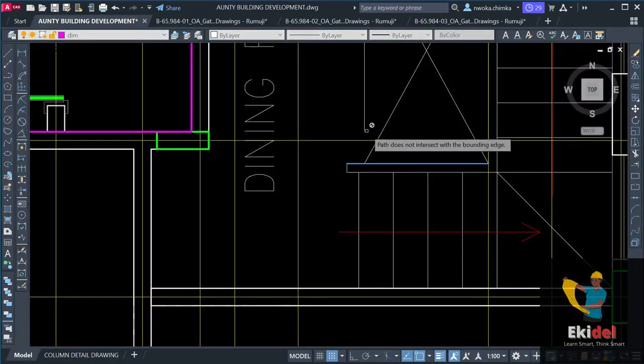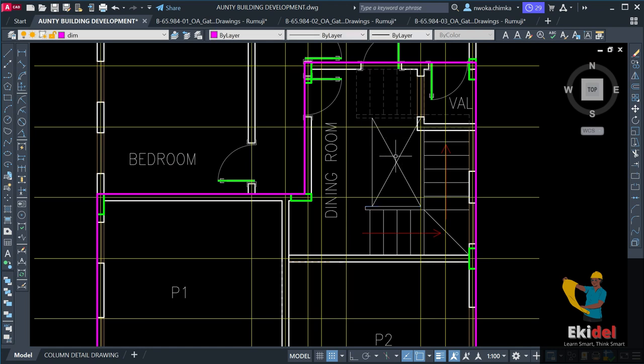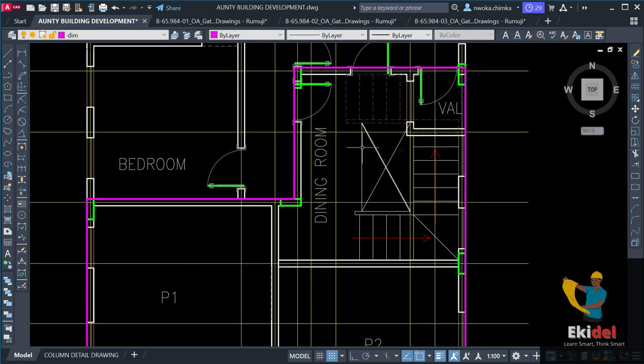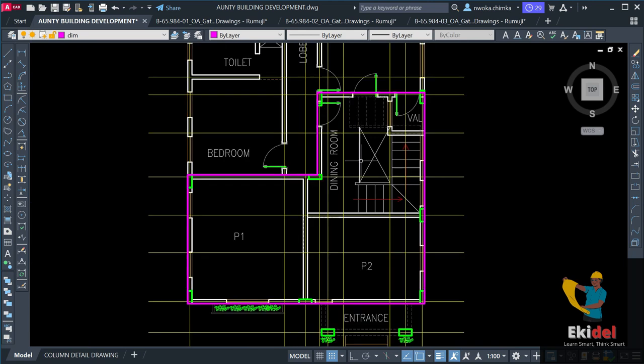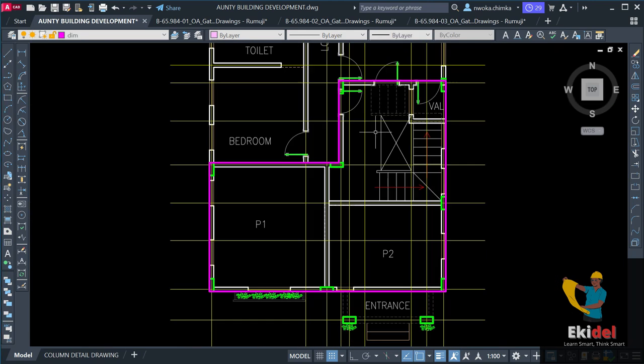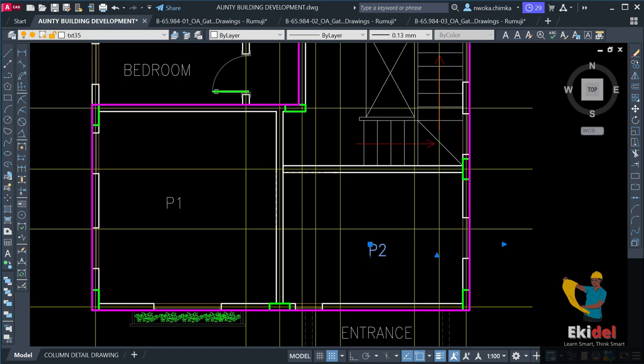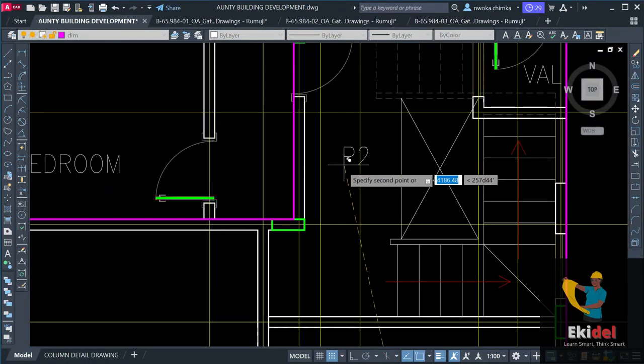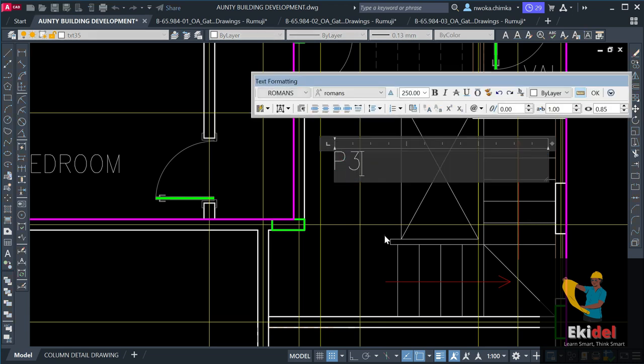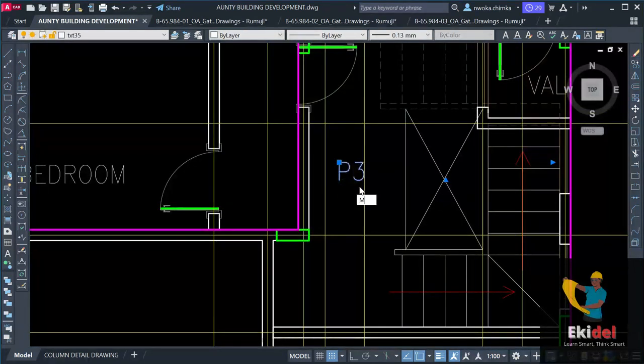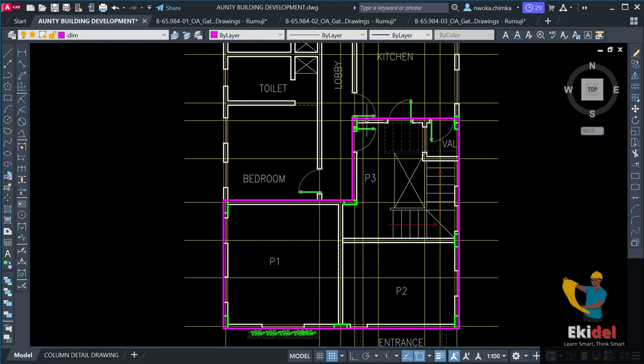The reason I picked that void to check on where our void is tells me that there won't be any slab on this area, because this is a void. So anything I'm doing about my slab will end directly at this place. So this place now we have to slab. So with that right now, I will remove this and call it panel 3. So just this area becomes panel 3. So along this area, let me just move this a bit. So along this area right now becomes panel 3.